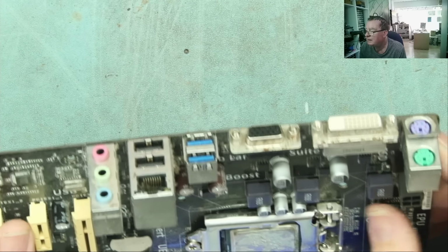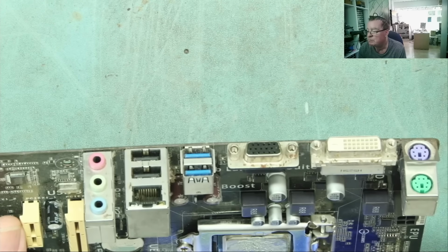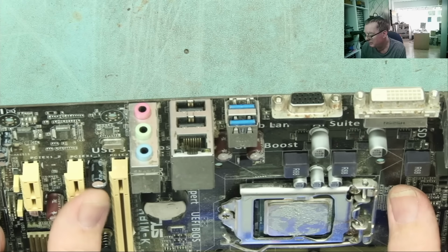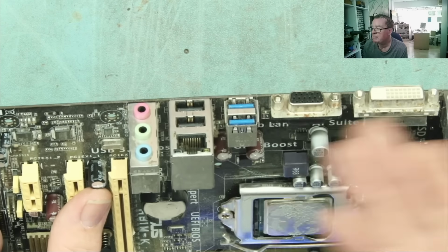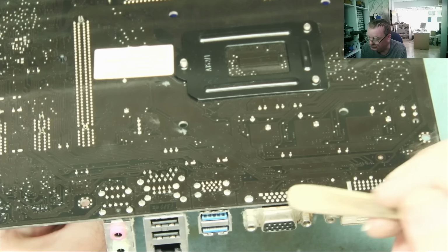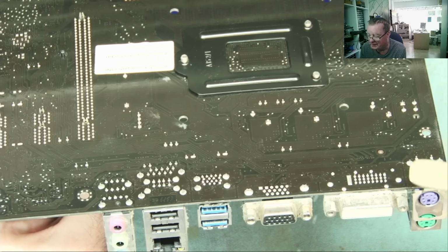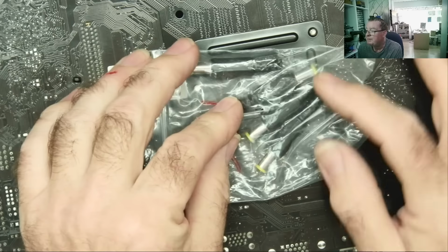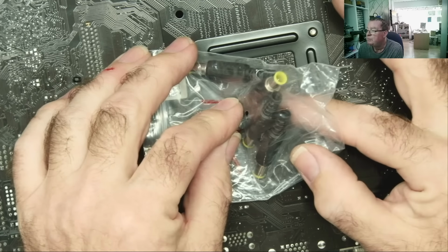You may think we finished talking about connectors, but we haven't. Connectors that connect to the outside world are prone to failure. Sometimes they will tarnish or corrode, because they're facing the elements basically. Again, quite prone to dry joints and fractured joints, especially things like coaxial power connectors. These type of things and the sockets they plug into.